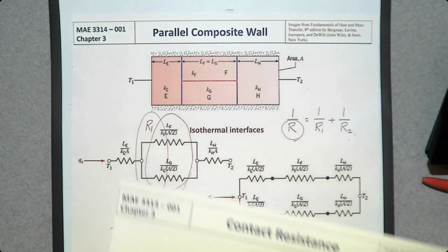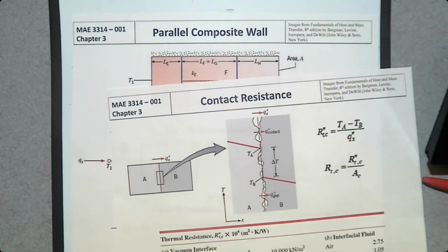And your question is going to be, how many times are we going to see steady state heat conduction problems? Most engineering systems are steady state. So when you work for a cell phone company, heat transfer from the cell phone is going to be steady state. When you work for a computer company, or this screen, heat transfer from the screen is going to be steady state. Why? If it is not steady state, it should be transient. That means initially 20 degrees Celsius. When you turn it on, it's going to be transient.